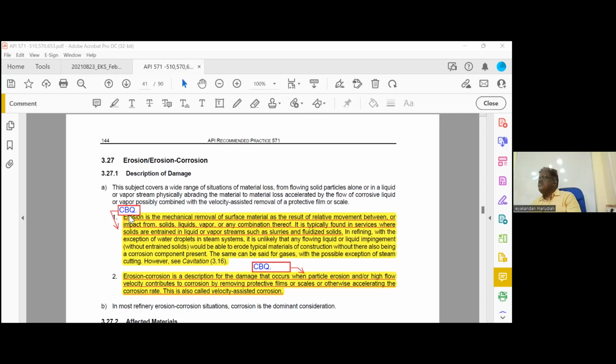Now coming to hardenability. I told you it is the entire depth. It is not only a surface property. The definition of hardenability is the depth of hardening by quenching. When you heat it and quench it, meaning cool it very fast, how much depth is it hardening? Hardenability cannot be improved only by carbon. It has nothing to do with carbon. It depends on the chromium and molybdenum percentage. When you have more chromium and molybdenum, it will have more hardenability.